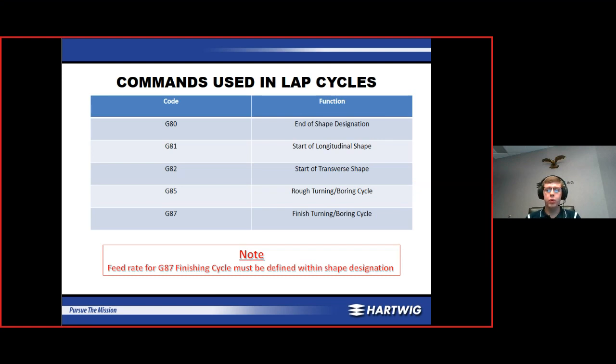So the reason we are going 5 millimeters in Z and 10 millimeters in X is because the Okuma control programs in diameter. So any command we give in X-axis is a diameter value, whereas the Z-axis is going to be the size of the chamfer. So when we cut a 5 millimeter chamfer, we can go to Z minus 5, but in X, we need to command double the desired size of our chamfer so that the machine doesn't cut it undersize.